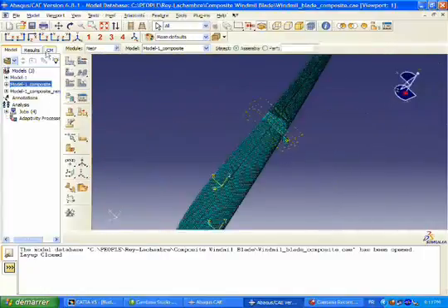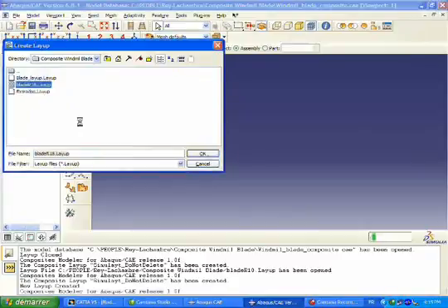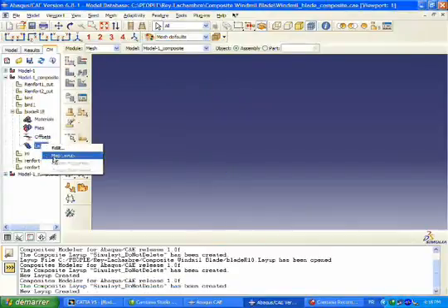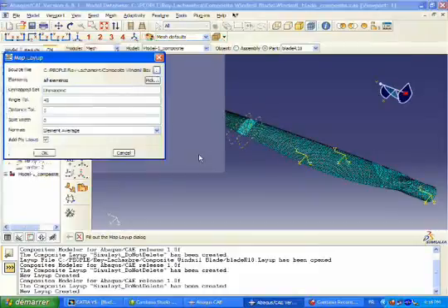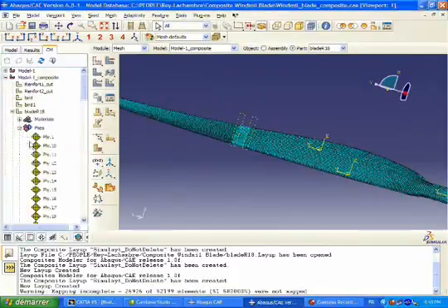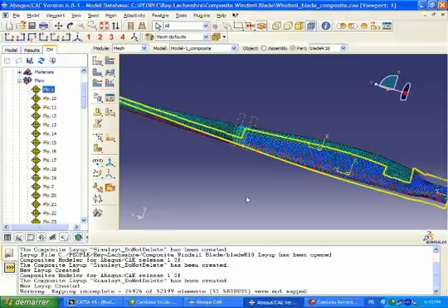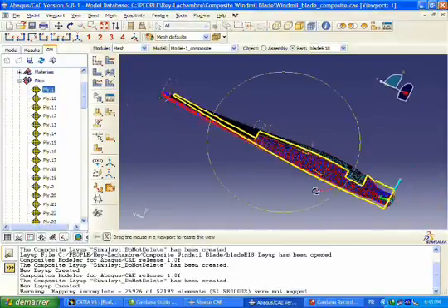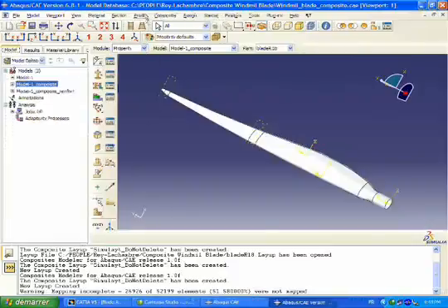So the first thing we're going to do is we're going to create a new layup. This is a layup that's going to reside within the Abaqus environment. And now we're going to map that layup. We're essentially going to import the layup that we exported from CATIA into our Abaqus model. So when we do that, we see that we have all of the plies that we had defined back in CATIA now in Abaqus and mapped onto our Abaqus mesh. So we had previously meshed this model, and now these plies and their relative orientations are defined on that model.